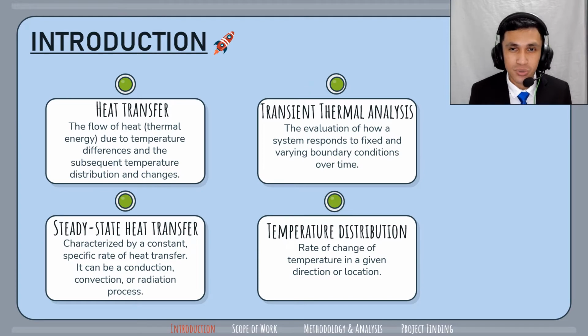For your information, what is the definition of heat transfer? Heat transfer is the flow of heat due to temperature differences and the subsequent temperature distribution and changes. Meanwhile, the transient thermal analysis is the evaluation of how a system responds to fixed and varying boundary conditions over time. In the physical world, heat transfer starts as transient and then reaches a steady state until thermal equilibrium is reached.